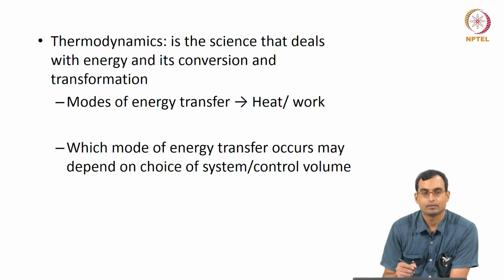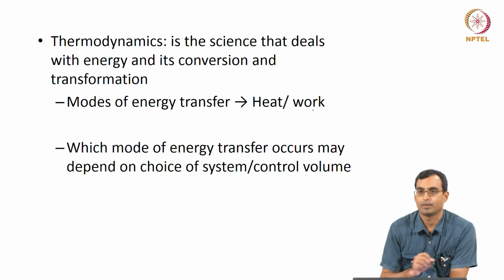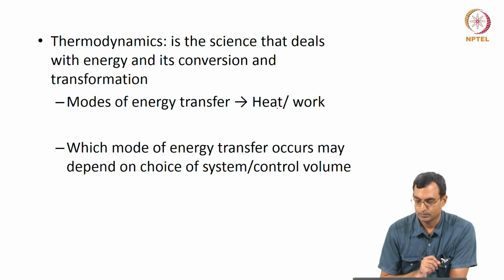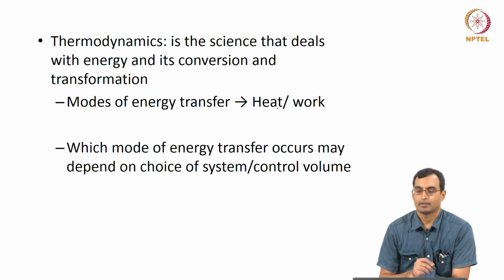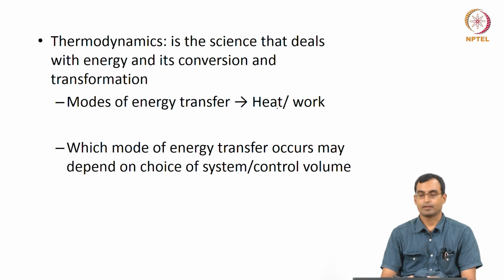We said that there are two modes of energy transfer, heat and work. We have looked at work in a bit of detail, so we will now go on to heat. Before we look at it, we will also emphasize that which mode of energy transfer occurs depends on our choice of the system or the control volume. Based on how we choose it, the energy transfer may be either in the form of heat or in the form of work.